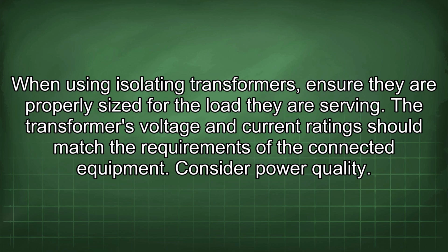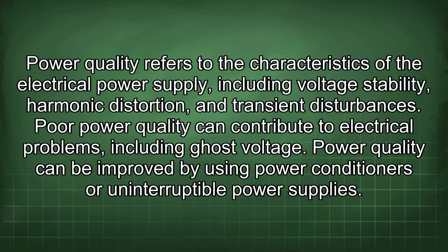Consider power quality. Power quality refers to the characteristics of the electrical power supply, including voltage stability, harmonic distortion, and transient disturbances. Poor power quality can contribute to electrical problems, including ghost voltage. Power quality can be improved by using power conditioners or uninterruptible power supplies.